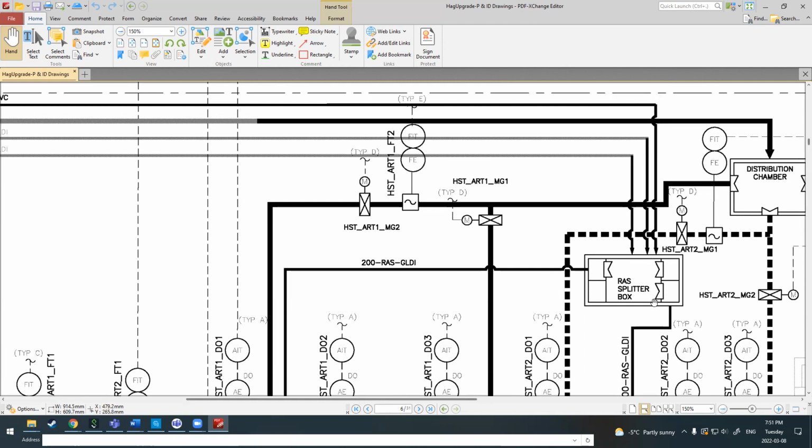These would be weirs. So a weir, how do you explain a weir? If you have water that you want to flow into certain areas, you would use a weir and set a very specific height. You would know that at 1 meter from the bottom of this V-notched weir is going to allow flow into these different sections of this splitter box.